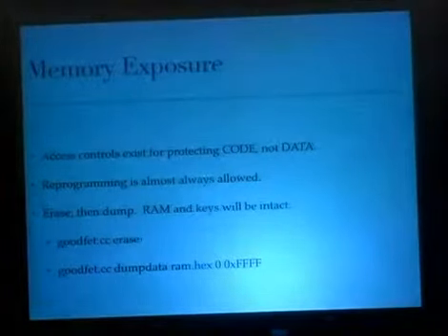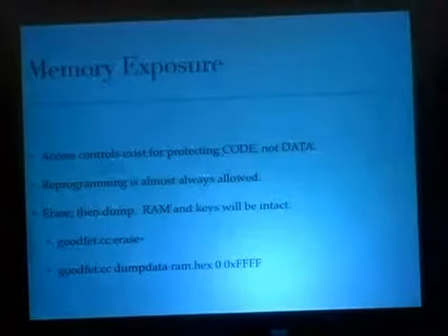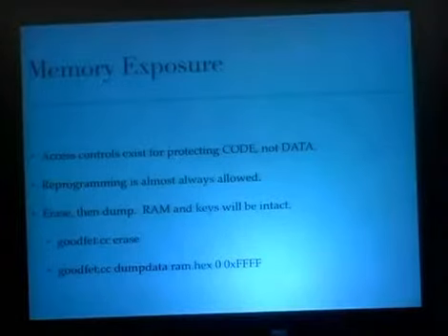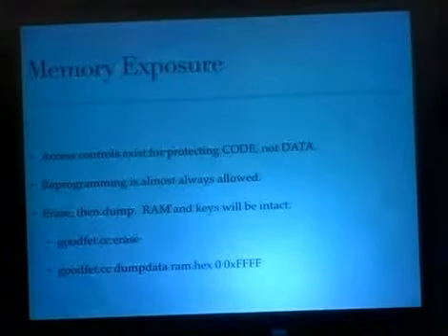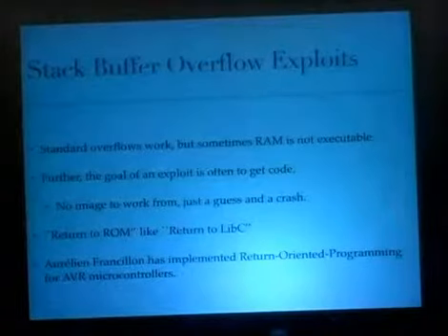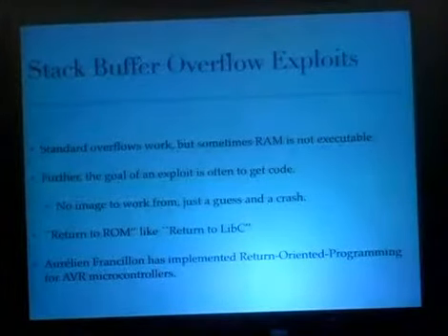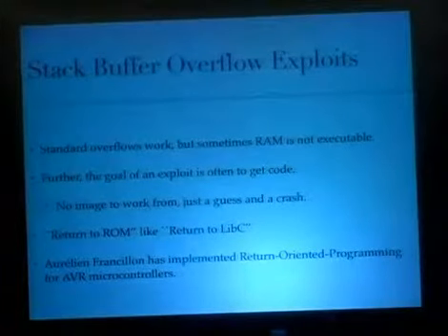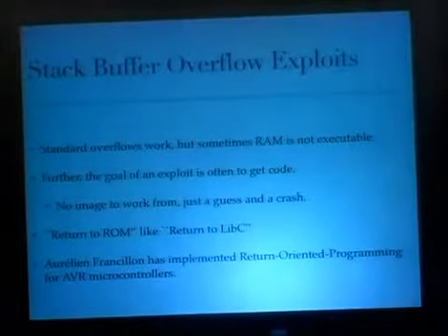You can look at it in the I/O region, and sure enough, there is a complete copy of every key in use. You only get the presently tuned frequency, but you can sort of guess at what the center frequencies might be, or at least catch some packets, if not all, should channel hopping be involved. You can do stack buffer overflow exploits, just as you can on a PC, except that there are no stack control mechanisms except for accidental ones.